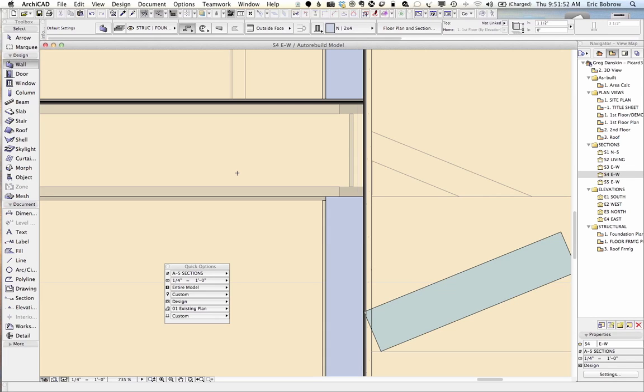So you don't have to type in numbers and sort of experiment that way. You can literally just drag them into which one's stronger. Now, what I typically recommend for something like this slab is that instead of calling this airspace, we call it framing, because air by itself, conceptually, you think of as not being very strong. But if it's a framing cavity, then it represents something that is strong.